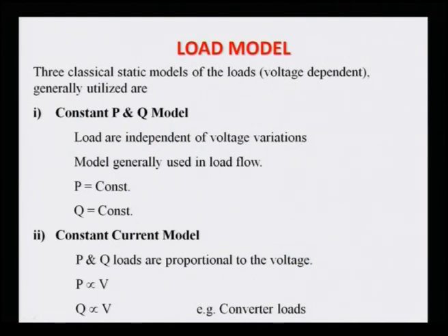So, with this we have the governing model, and now we have to go for load modeling. So, let us start the load modeling. As I said, it is the fourth component, that the load should also be modeled accordingly depending upon the needs. In the classical analysis of transient stability, normally the loads are fixed, but if you are going for the detailed analysis of transient stability, then you can model the load accordingly.